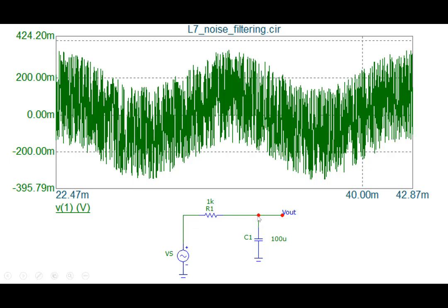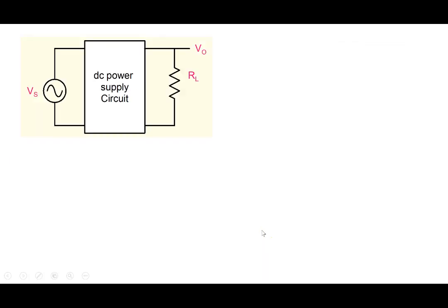Okay, because for a capacitor to follow something, the capacitor has to charge and discharge. And the charging and discharging of a capacitor, you would remember, would be controlled by how much current can flow from here, because the current has to supply charge and the current is controlled by R. So if you don't have enough current, or if the R is high, then the capacitor can only follow the slower signals, and the faster signal the capacitor will not be able to follow. And that's how the signal gets cleaned. The high frequency noise components get rejected, and the signal of interest then remains here. So we're seeing a very important role that the capacitor is playing here in signal processing.